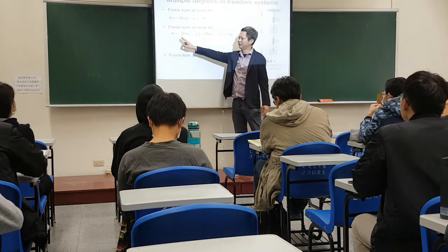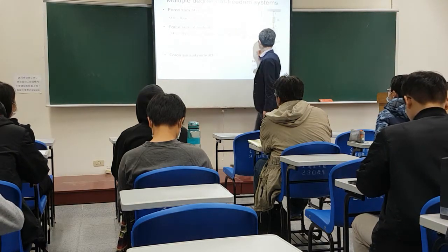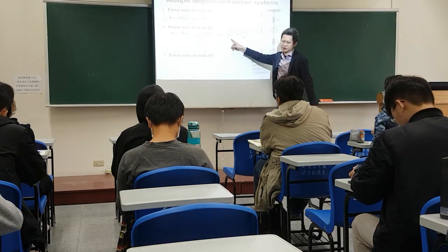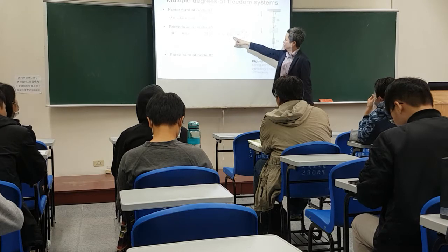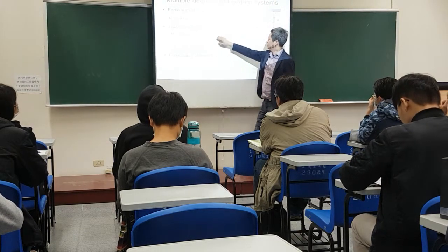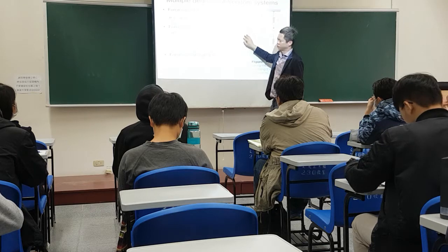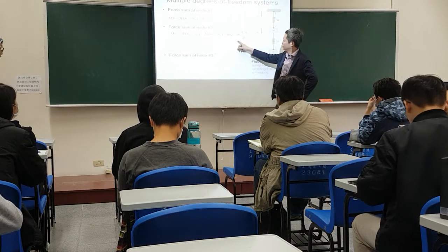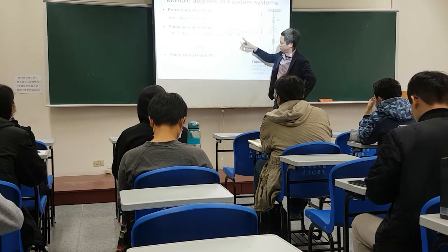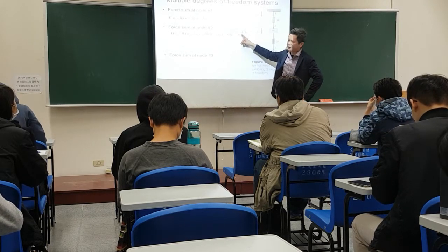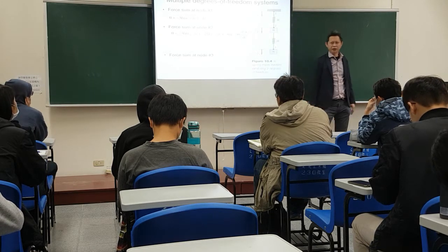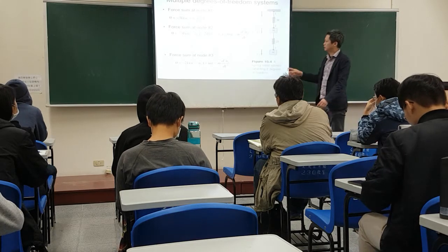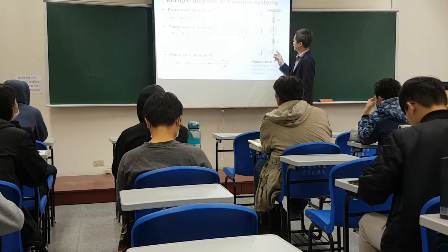Take for example, if you're writing Newton's second law, you're writing mass times acceleration is equal to the force summation. But here we are writing all the force summation minus the inertial force. So when acceleration is going downward, the inertial force, when you write in the force balance form, Newton's first law form, it's got to be written as minus inertial force, minus mass times acceleration. Likewise for the third mass.